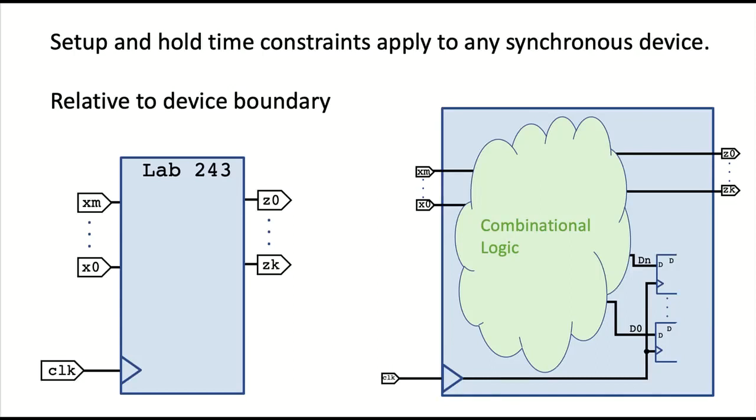A company might tell you, hey, I have this component with a negative hold time. That sounds strange. What's happening is that the inputs take so long to get here that you can actually change them very soon after the clock, because they won't make it here until the real hold time has expired.